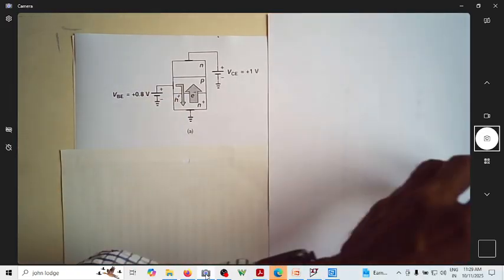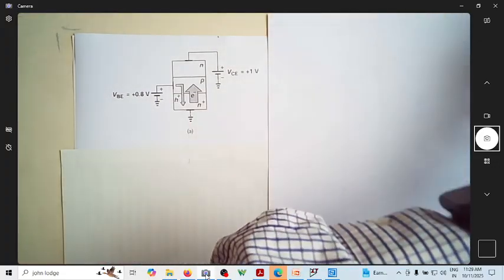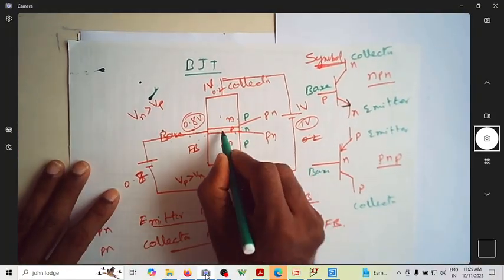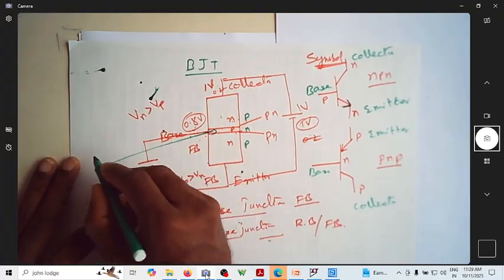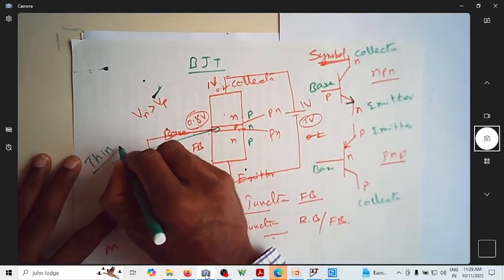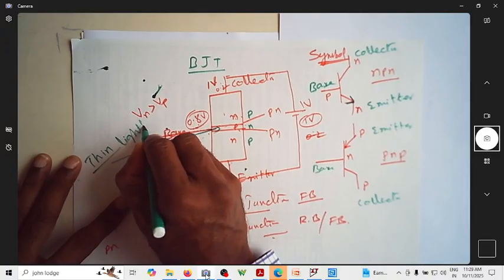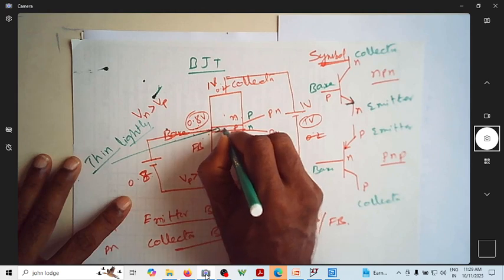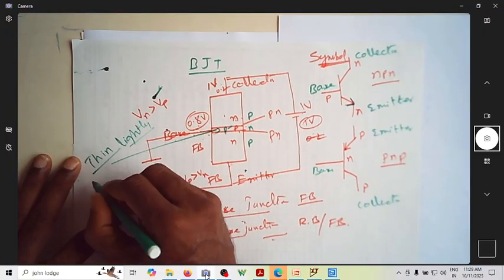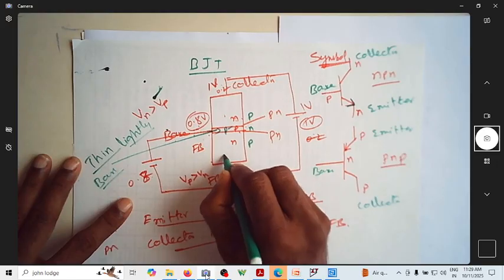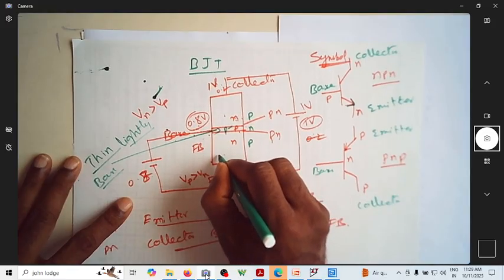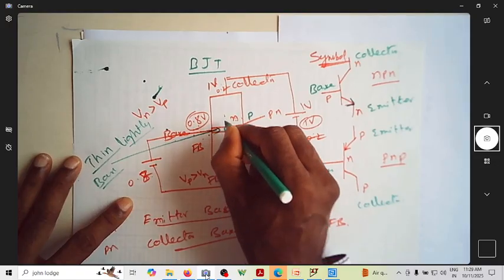And one very interesting thing I forgot to say is, in this case of BJT, this base is thin in dimension. It is very thin and it is also lightly doped, so it's basically like P minus. Thin is the base structure, whereas the emitter is actually heavily doped. So even though it is NPN, it's actually N plus, P minus, and N.